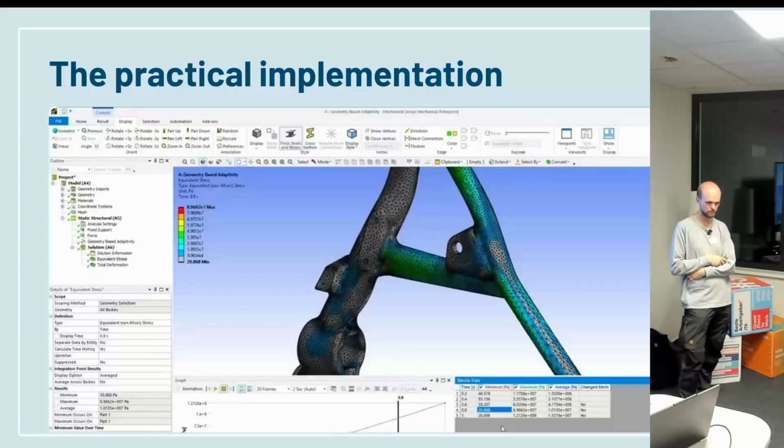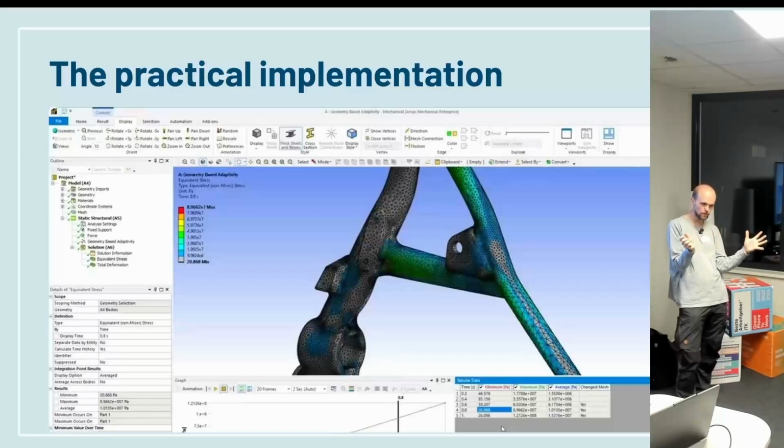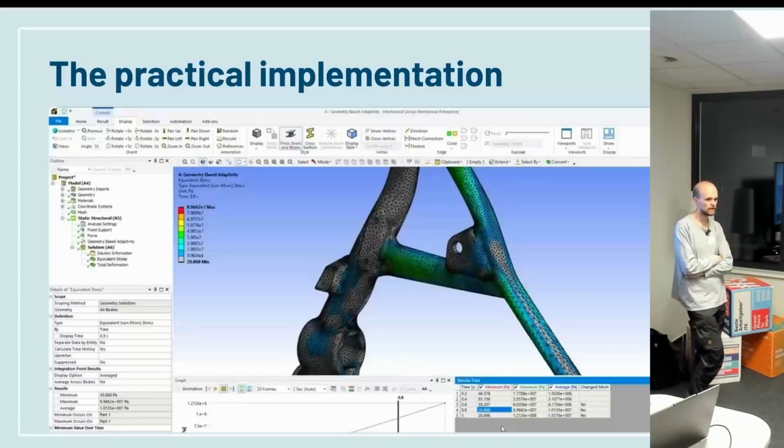So all the elements are on the surface and not inside. It's a full volume, yeah, because we have to calculate the energy over the whole thing. Yeah, that's why you also need the internal structure. Okay. You can do only surface elements, but that only works if you have a thin structure like sheet metal, and then do different math to account for the element thickness.